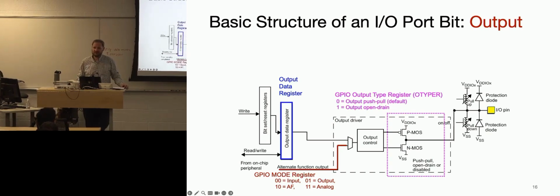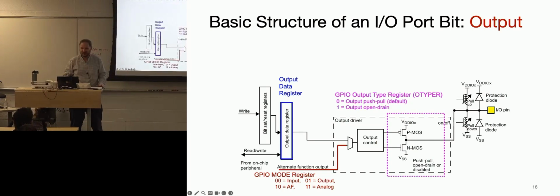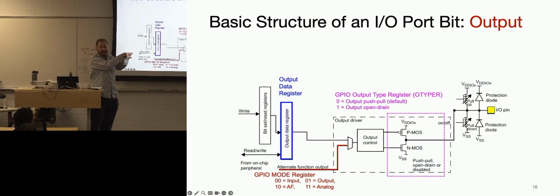Correct. With analog, you're reading more than 1 bit. So we have a whole unit on analog to digital converters. An analog to digital converter is a way to get the outside, that soft human world, into this digital world. It's a device that will measure the voltage between 2 points, VDD and ground, let's say, and tell you what the digital representation of that voltage is.